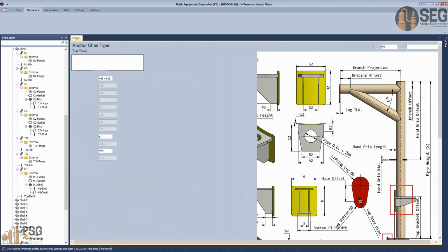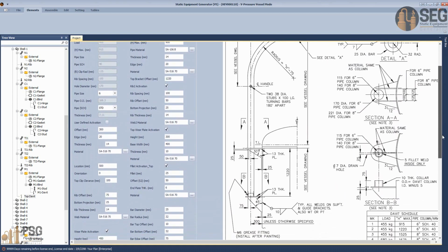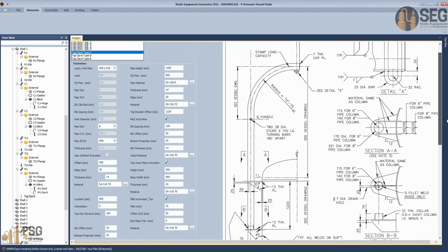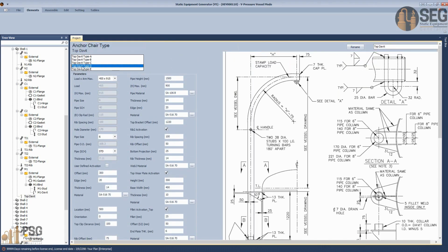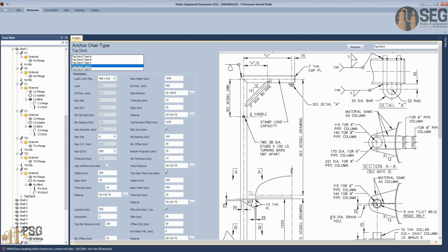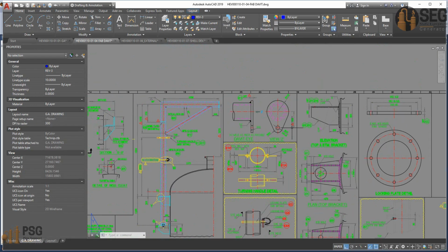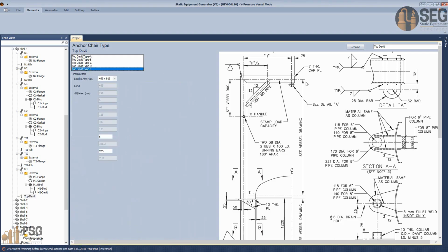Another type, which is type C, is related to another standard spec, so you can use this type if it suits your requirements. Another type of the top davit, like that, and the lifting lug here is just a U-bolt, but in our case it's a blade like that, so that type will not suit our requirement.